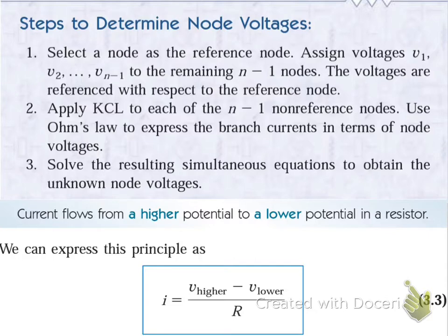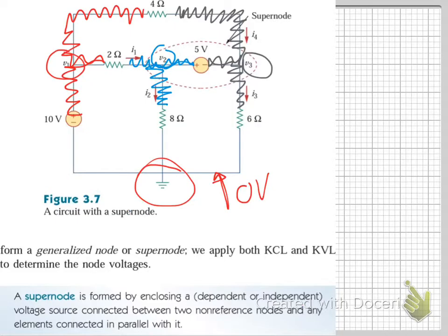It doesn't really matter which order you assign the voltages, but in the test, because you're still in first year, they want to assign you the nodes. They want to tell you this node is V1, that node is V2, and so on. You know what I'm saying? And then you do KCL at the nodes. So basically, you can see all of these arrows: currents.